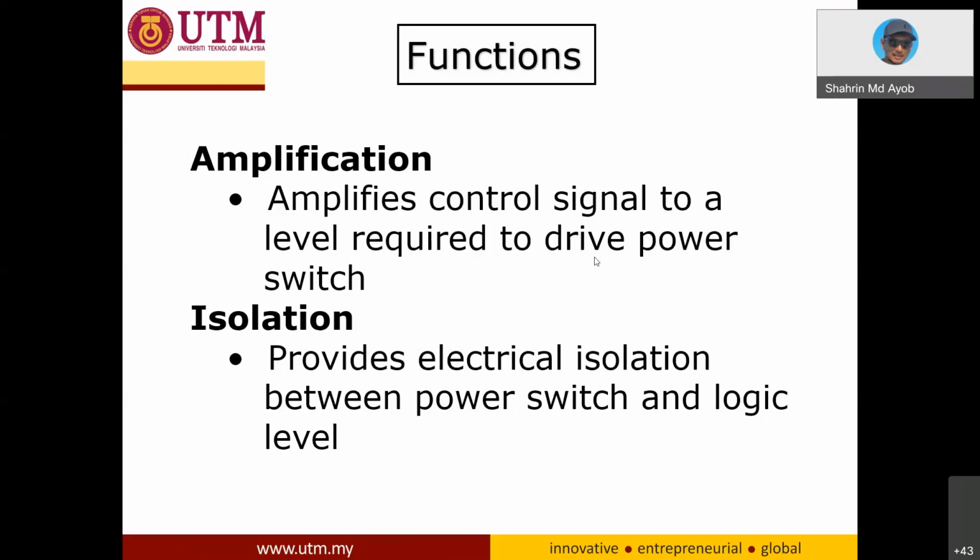The second one is to provide electrical isolation between the power switch and the microcontroller. You plug that microcontroller into the computer, right, using USB or any parallel connection.